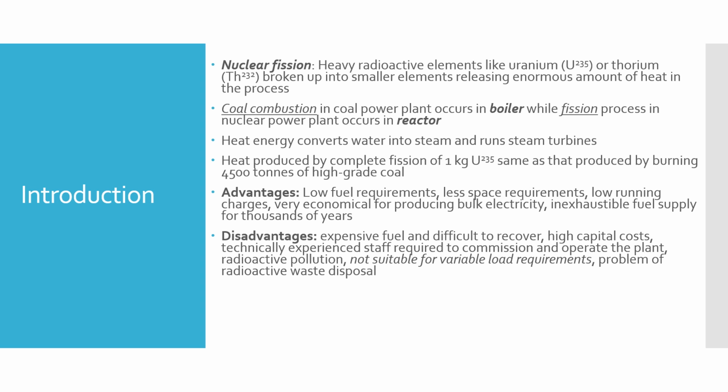The capital costs involved with the plant are high, obviously because you have to shield against radiations emitted from the plant. You need technically experienced staff to commission and to operate this plant, and radioactive pollution is produced because the waste which is produced by the plant, once the fuel is spent up and used completely, is radioactive waste, and that generates radioactive pollution even if it is disposed of properly. It is not suitable for variable load requirements, obviously because for very fine adjustments you cannot vary the output of the plant that much.